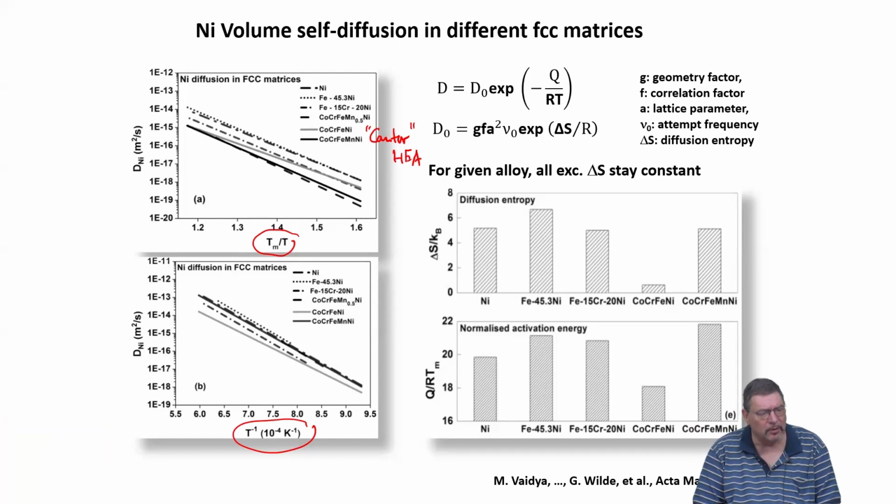And importantly, we measured these diffusivities for all constituents, all 5 components, in comparison to this quaternary alloy, which doesn't have manganese. Also there, all the 4-component self-diffusivities were measured for volume self-diffusion. And they are compared here now with different matrices. Matrices meaning alloys, or in one case, pure metal, nickel. All of them are FCC.